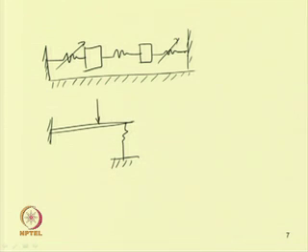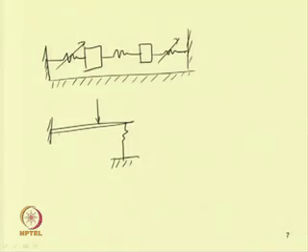In this case, as the cantilever beam is a continuous system, it can be modeled as an infinite degrees of freedom system. Also, one can take a finite element formulation. For transverse deflection, if one takes a beam element, then for each node one can take the displacement and slope as degrees of freedom. For the ith node, this is the displacement w i and the slope, that is, del w by del x.